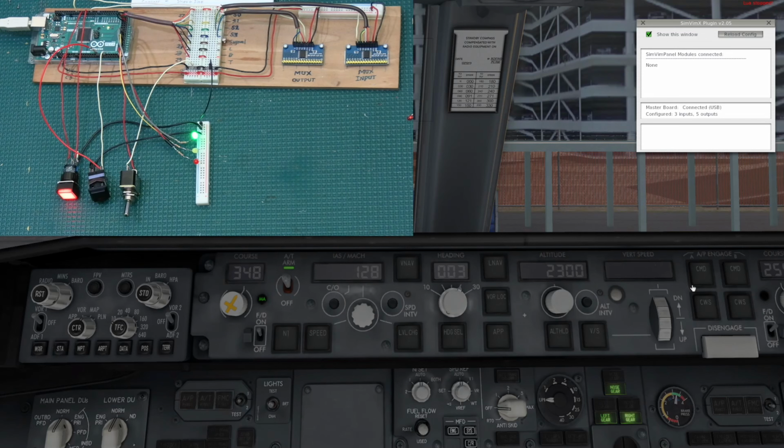You know, the command does not light up, but I am getting that warning light, which is the one that we're seeing right here in our physical buttons. So now I can go ahead and push that one and clear it. So that's good. And then right now the auto throttle is on, as you can see right here, because my toggle switch is up. So if I put it down, we should see that red light come on right there. So yep, there it is. So that's working properly. And if I turn it back on, that red light should come off, which is exactly what the sim is doing.